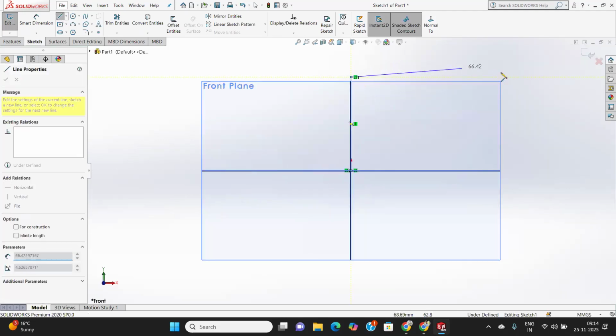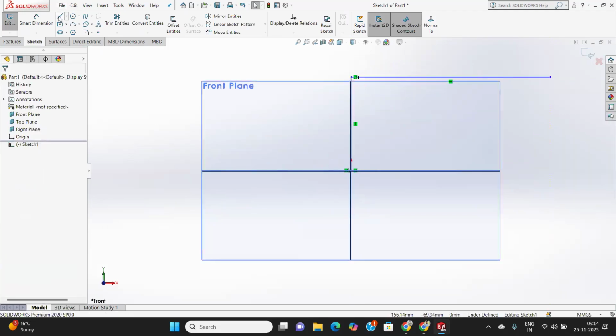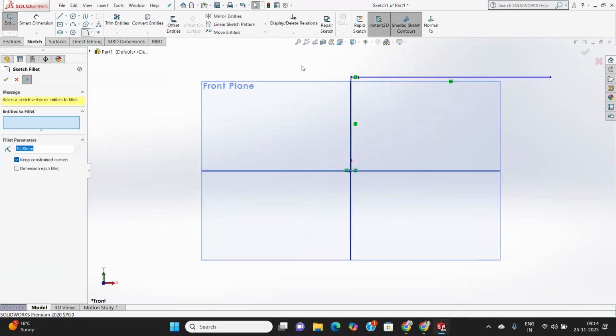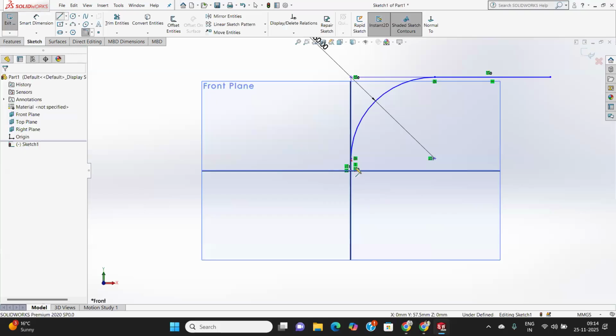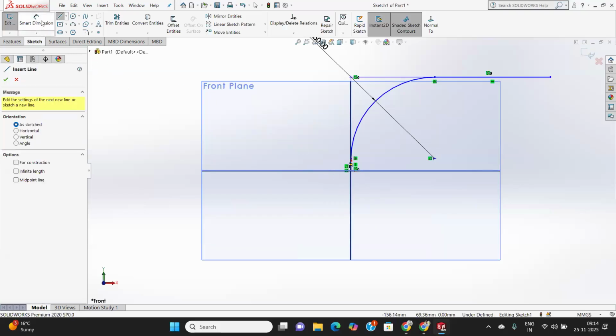to this way. Right click on it and then I just write here. And then what you do, fillet on it. I just fillet this portion. And then I increase my fillet radius to 50 mm right here. And then I just note this.